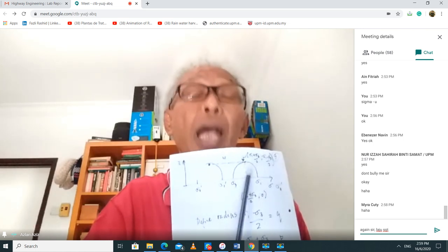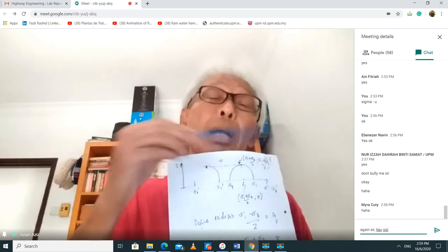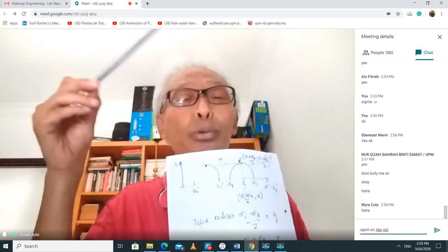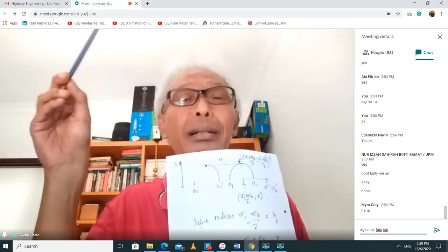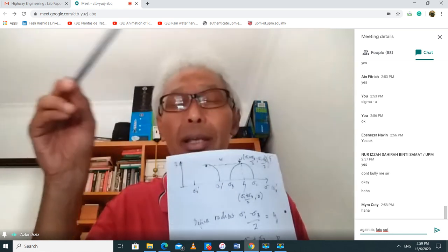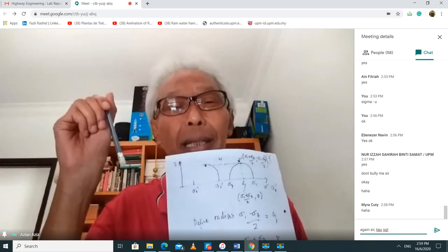All right. So now I'm moving away from defining failure as tau equals C plus sigma tan phi, which relates the shear stress and the normal stress, with the cohesion and the phi value.